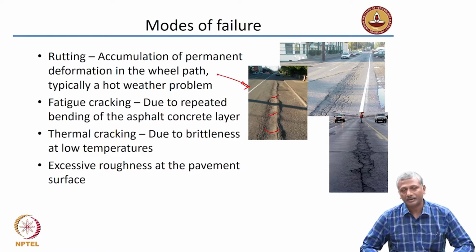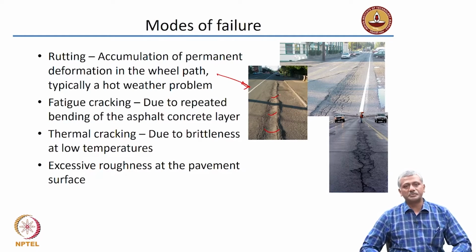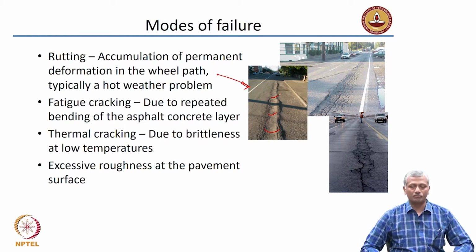That is called rutting. And rutting is a very common phenomenon, especially in summer months when you have significantly high temperatures, and that may cause the asphalt to start flowing.